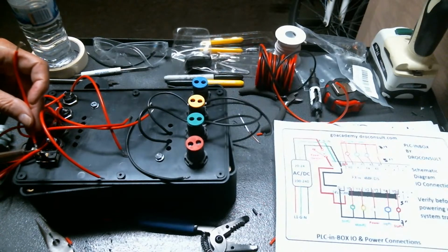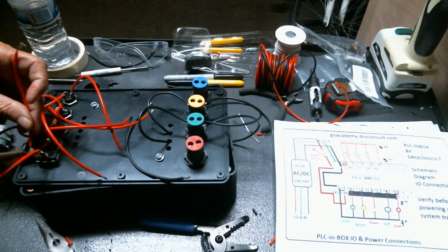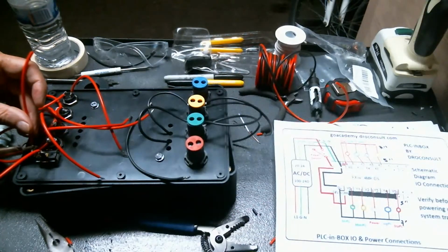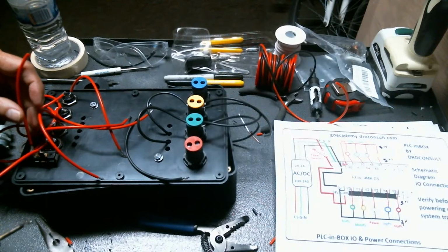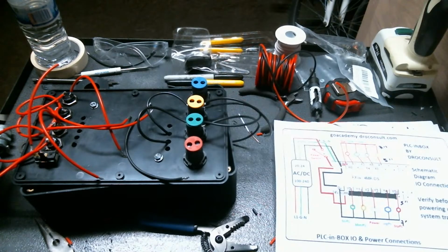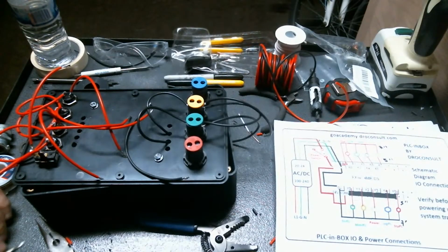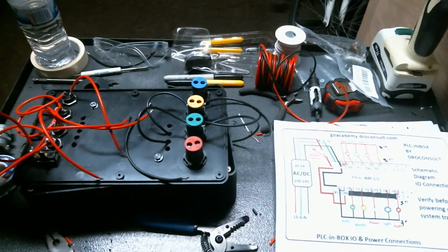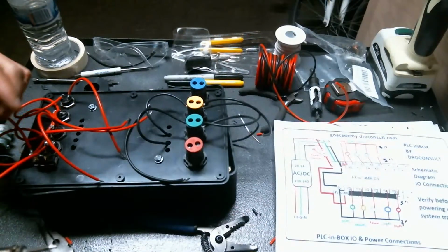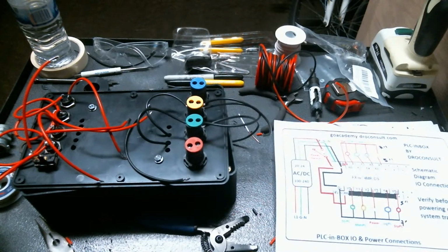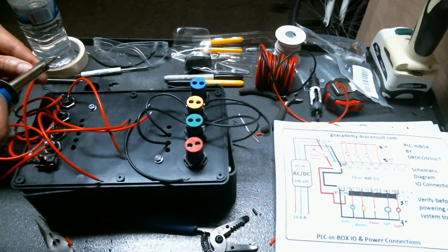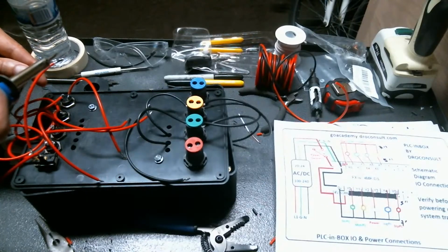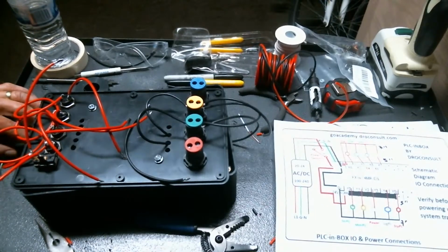Okay, so you just have to be patient with yourself. I think I got it. I'm going to add a little more solder here on top just to be safe. So again, this is going to be my power cables that will bring power to the board. I'm going to pre-tin this here. Pre-tin. I found that pre-tinning the wires actually helps us do a better job.